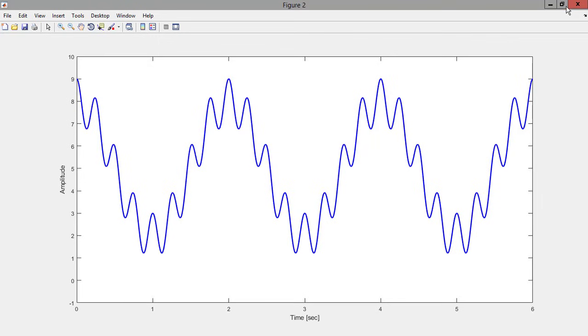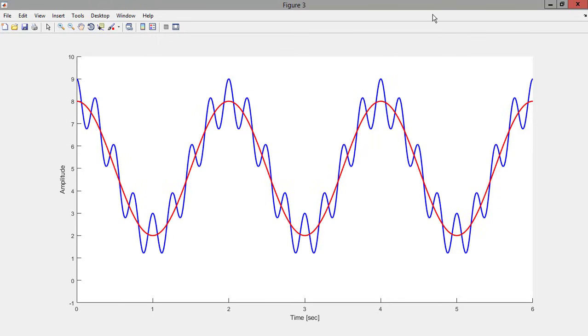amplitude spectrum plots, right? So to begin this problem, we need to appreciate that there is a fundamental sine, or in this case cosine wave, that my final plot is plotted on top of. There's a higher frequency component as well. But there's this 1/2 hertz frequency component. I know it's 1/2 hertz because it completes 1 period in 2 seconds. And that fundamental component's going to go basically right through the middle of the blue curve that's on the exam.